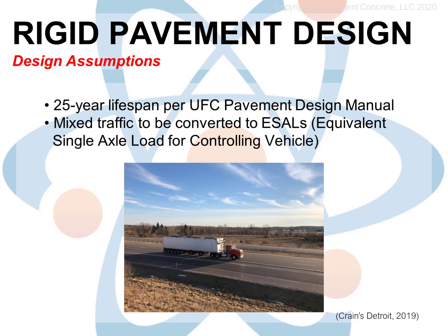That is, it is considered the vehicle capable of having the greatest impact on pavement wear and distress, with the philosophy that other, perhaps fewer or lighter vehicles will be able to use the pavement and not cause any adverse impact. The reason for converting traffic to a single variable is to simplify the design process and to bring everything back to a single point of reference.